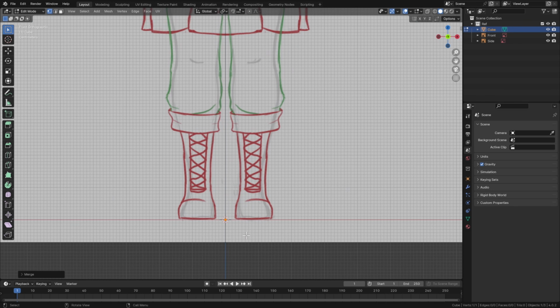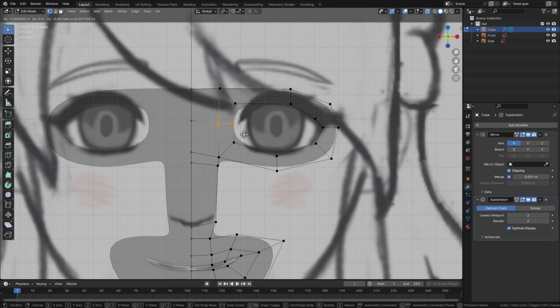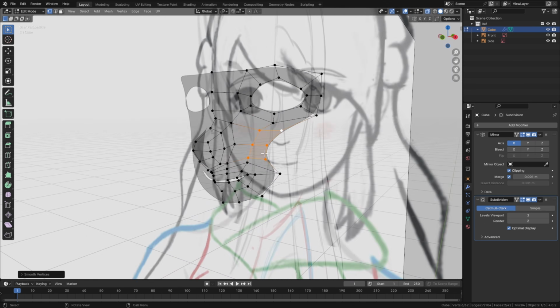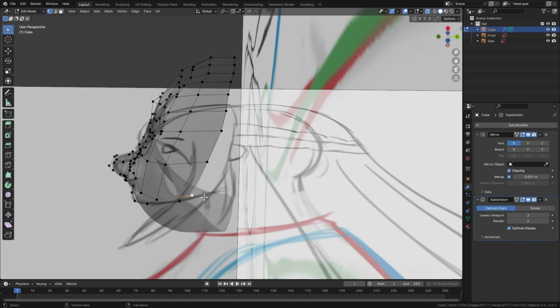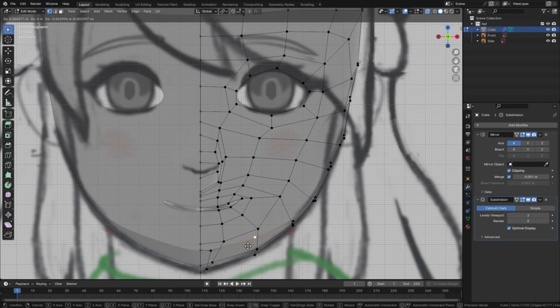When we build the head, we are actually going to start by making the proper topology for the eyes, nose, and mouth first. I've experimented with several approaches, but this was what I found worked best in my practice. We will make a vertex, add some modifiers, and construct the loops together to form the shape. With the core edge loops, we will then adjust it in right orthographic view so it has a proper 3D shape. Then it's actually not too difficult to fill in the rest of the head and neck from there.